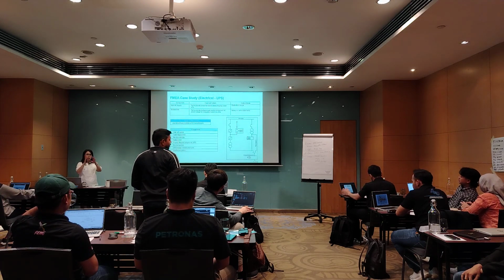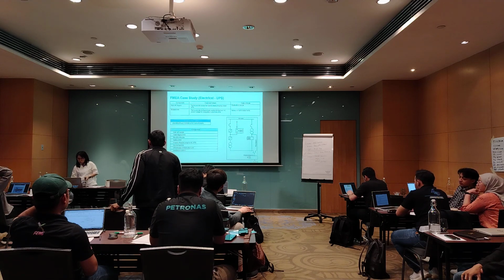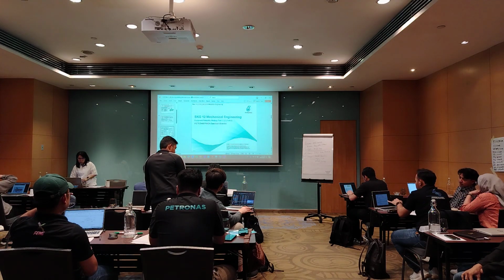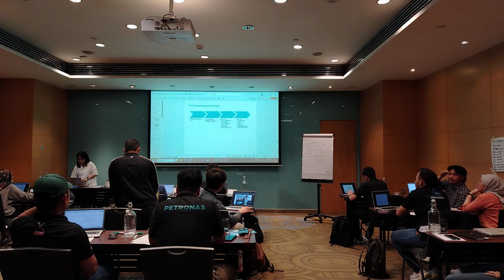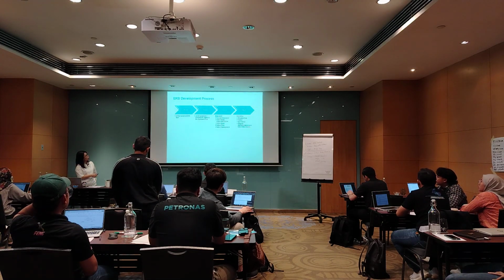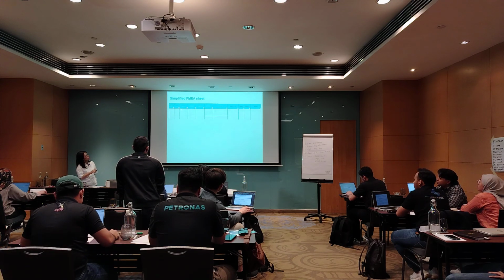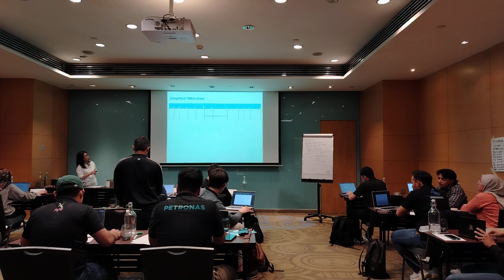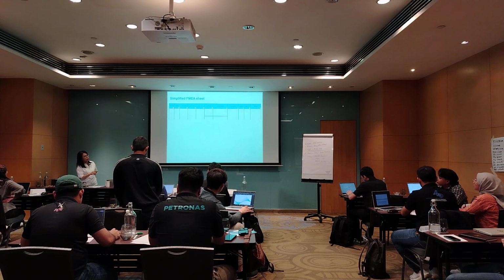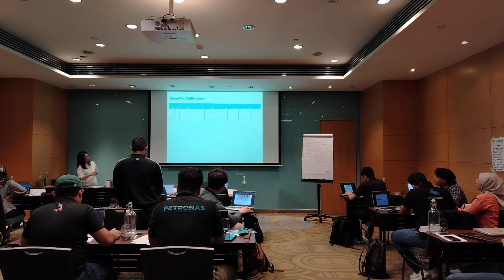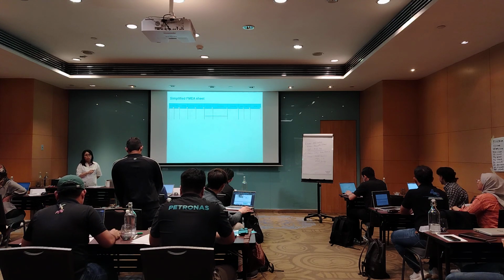Put it in landscape mode. Your template will look something like this: component, function, failure mode, mechanism, cause, effect, consequences. Then mitigation. Who does it? How frequent do you do it? Any remarks or not?